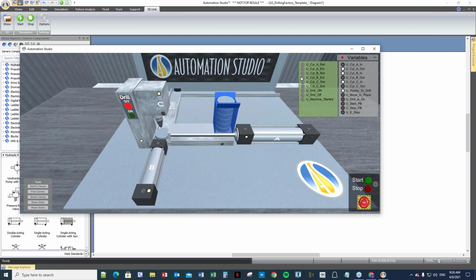extend the B like that, and then retract my cylinder, and then retract my cylinder here. And so this is my sequence. Basically, push the cylinder A with a disc over here, and then once it's here, pushing it over there, but no drills. So just moving discs in the system.